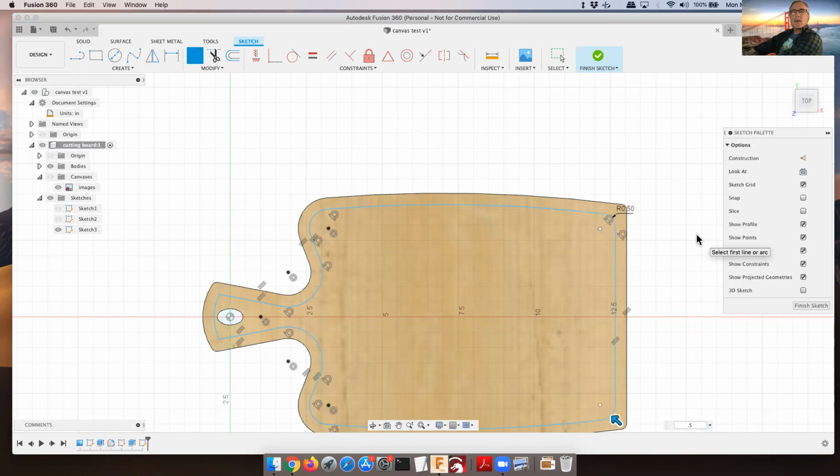Hey, Tim, when you got those corners, because you went from your 3/16 inch fillet and you tightened it up as you did the inside offset, correct? Right. As it did the inside offset, it got smaller and smaller until it reached 0. Got it. In the early days of CAD tools, the math would fail when you went on the other side. Now they're smart enough to figure it out. They just take it to a sharp corner. If I'd gone out this way, you would see that radius just continue to grow, just like this radius here grew. But this isn't really what I want here either, is it?